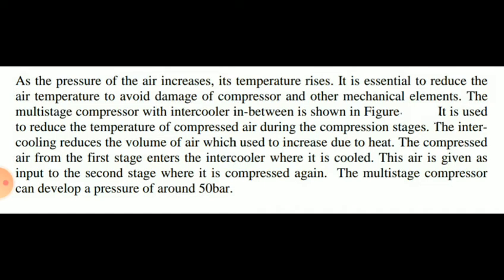The intercooling reduces the volume of air which used to increase due to heat. The compressed air from the first stage enters the intercooler where it is cooled. This air is given as input to the second stage where it is compressed again. So the multi-stage compressor can develop a pressure of around 50 bar.